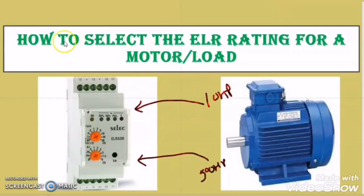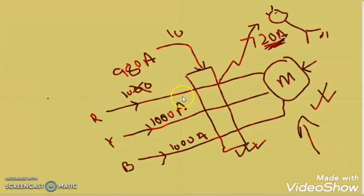This concept is very important to understand how to select the ELR rating for a motor or for any load, as there is no straightforward calculation to select the ELR. What I said so far is that the ELR's purpose is to protect the human. So the ELR will not care about the load, how much current the load is taking. The ELR will care about how much current is leaking. And if the leakage current is more than the dangerous level that can harm the human, then it will trip the circuit. Hope I am clear till here.